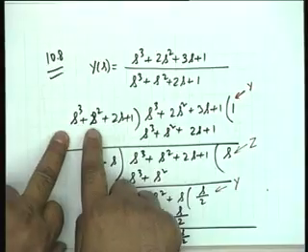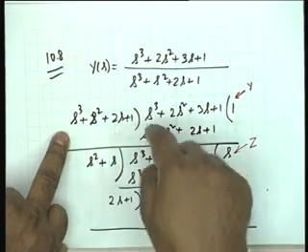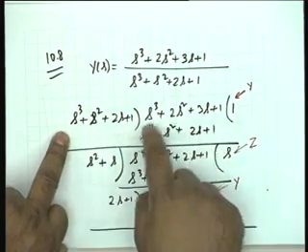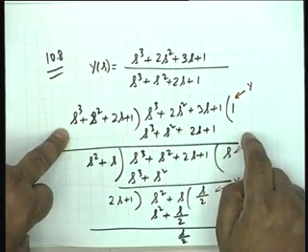So how do you do continued fraction by lowest power? You write it in the reverse fashion. That is, start with the lowest power. Instead of s cube plus s square plus 2s plus 1, you write 1 plus 2s plus s square plus s cube. Similarly here also 1 plus 3s plus 2s square plus s cube. Quotients will be 1 upon s. You know that. And 1 upon s, if it's an impedance, then you know it's an inductor. If it's a capacitance, you know it's a capacitor.